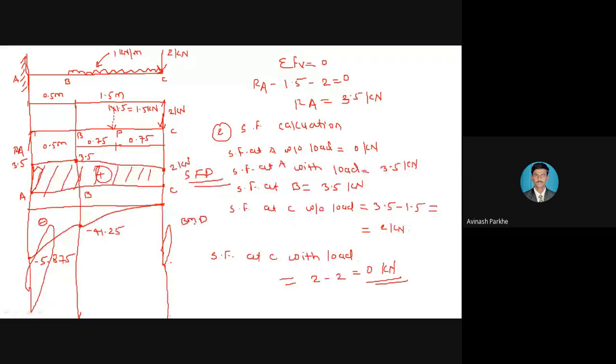That's why yesterday also I told, in case of a cantilever beam, whatever shear force diagram you get, for 90 to 95% of problems the SFD can be obtained in the positive region only, and your bending moment diagram can be obtained in the negative region only. Otherwise there are some 5 to 10% problems in which if we change the magnitude of load, maybe in the upward direction, or if the cantilever beam is subjected to a couple, at that time there are chances to convert your SFD from positive to negative, or your BMD from positive to negative.